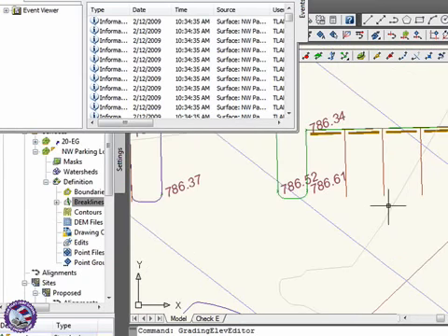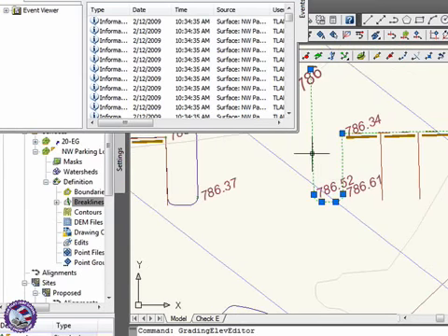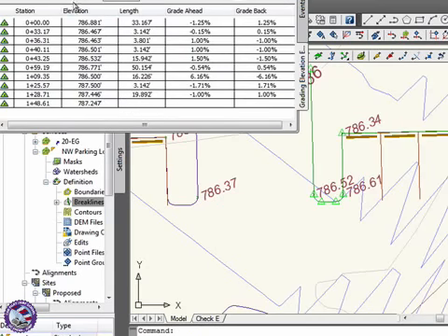it should be. It shouldn't affect it dramatically, but if I pick the elevation editor, and change my increment and just make it 2 feet and raise all the elevations, right, by 2 feet, you can see the surface modifies itself, right, in the background. So extremely dynamic, and the more of the dynamic stuff you throw in there, right, you better make sure you're backing up.